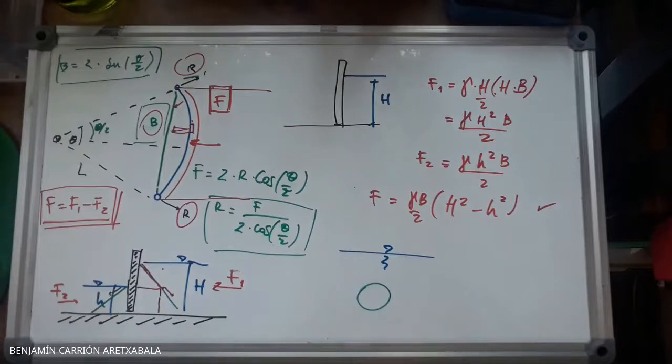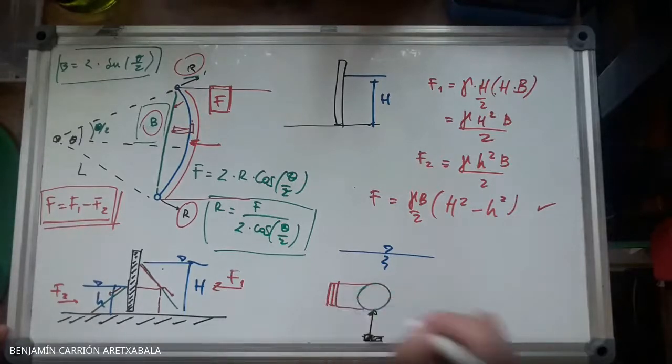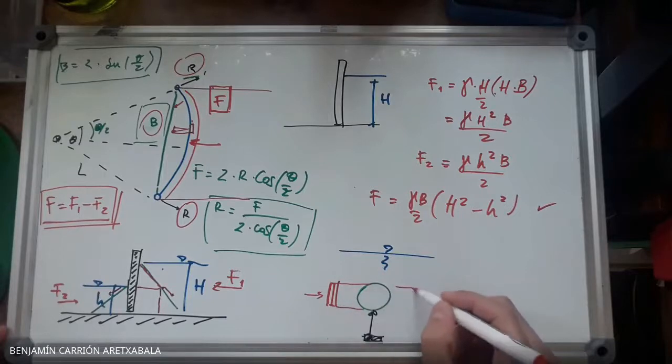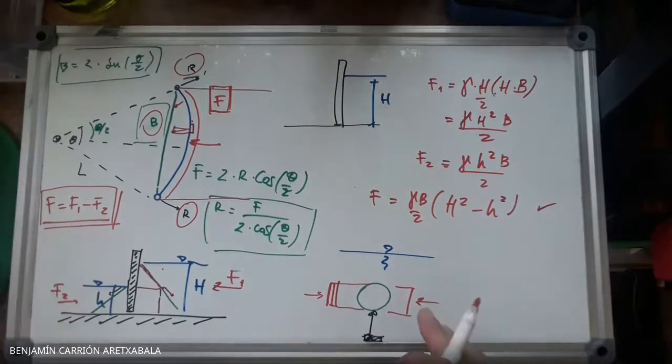Let's say it has a string, so it's tied to the bottom. You have to realize that the lateral force is nothing more than the projected area. So along this area, there is a force acting that way. And of course, this is the same in that direction. So the net lateral force is zero on a submerged body.